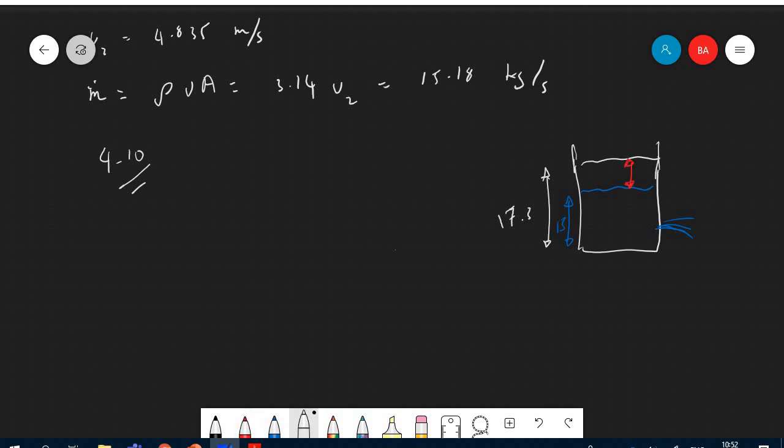What is the diameter? The diameter of this thing here is 15 feet. Okay, so we can say pi d square over 4. We can get the area. That's the area, right? If you multiply it by 4.3 feet, you're going to get the volume, and this volume is going to be important information because it tells you how much had been spilled.